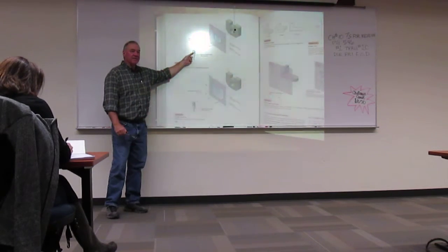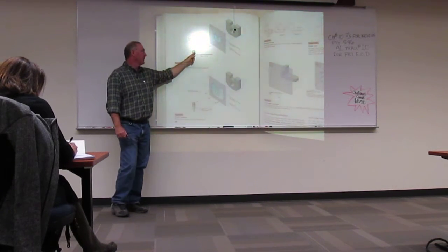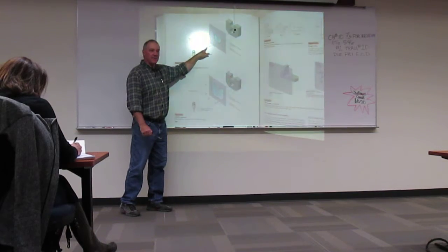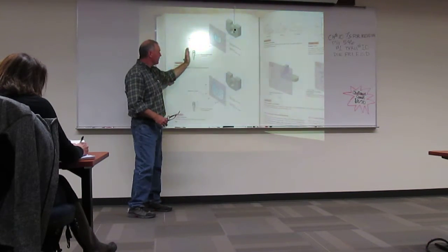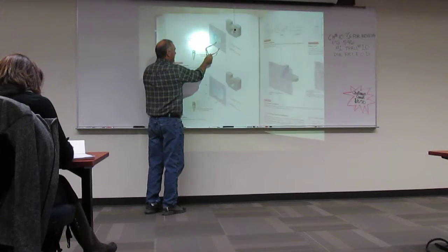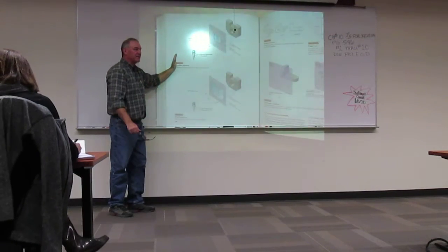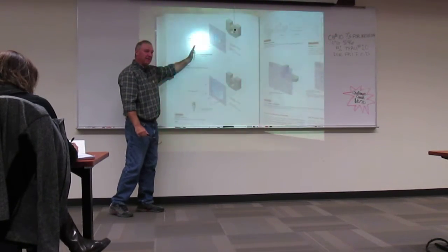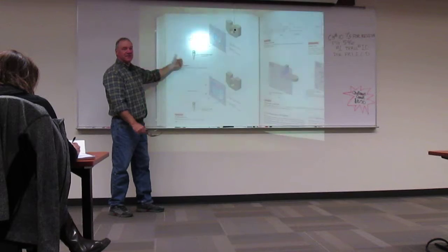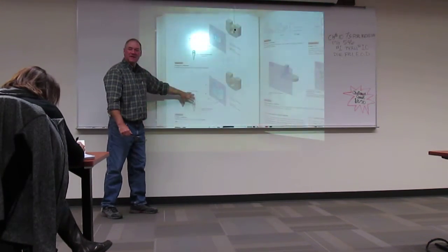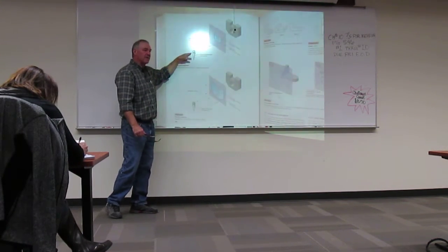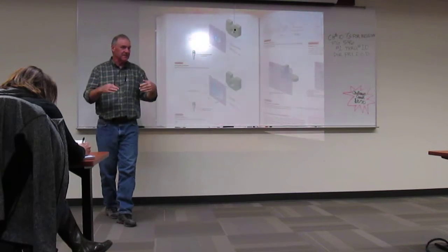Here, we define the location. Therefore, there has to be angles coming from here because we know where this person sits. Now, the further this person gets away, the less that angle becomes. And so for parallel projection, we say, okay, let's just move you back to forever. That's kind of another word for infinity. Then that angle gets smaller and smaller and smaller until it disappears.